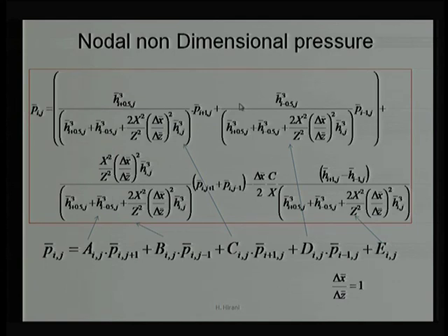Now, from a computational point of view, it is always advisable to non-dimensionalize first, and when non-dimensionalization is happening and both x and z values are the same, like the maximum values along the x axis and z axis are the same, then we should take the same spacing. The number of nodes in the x direction and z direction should be the same, because we have non-dimensionalized in such a manner that they vary from 0 to 1, they have similar kind of magnitude values. So, we should take an equal spacing.